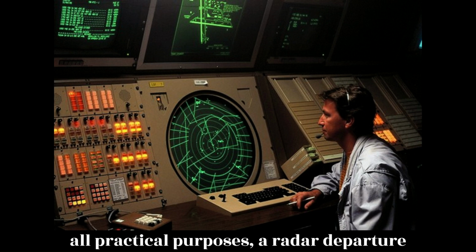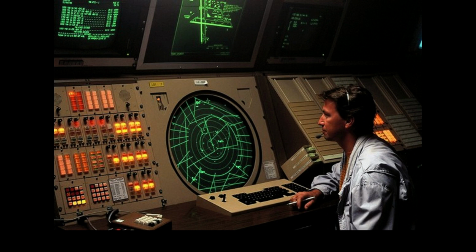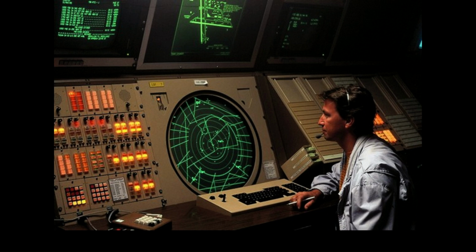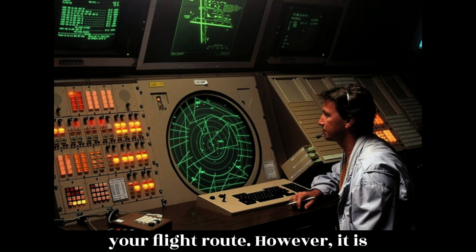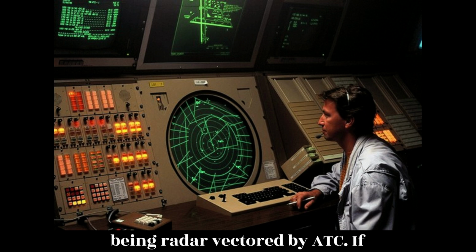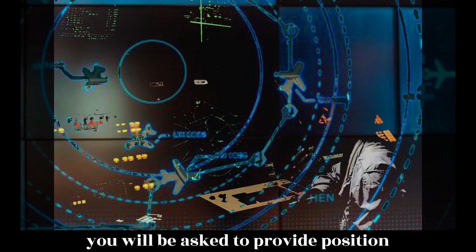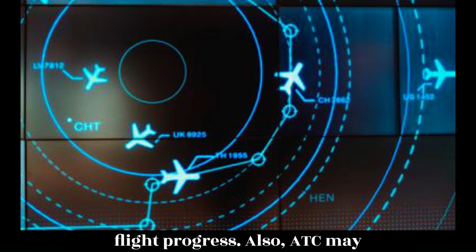For all practical purposes, a radar departure is the easiest type of departure to use. It is also a good alternative to a published departure procedure, particularly when none of the available departure procedures are conducive to your flight route. However, it is advisable to always maintain a detailed awareness of your location while you are being radar vectored by ATC. If for some reason radar contact is lost, you will be asked to provide position reports in order for ATC to monitor your flight progress.